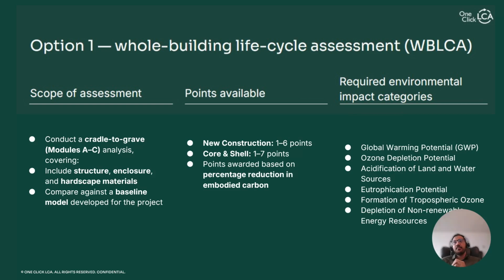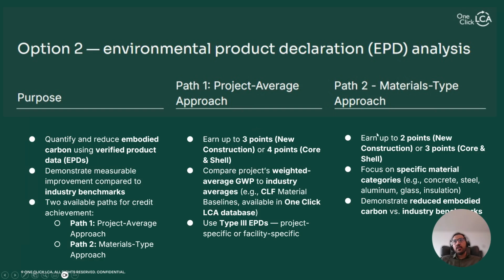GWP, as I said. But for the report, you need to report all these 6 environmental categories, which is going to be available in the TRACI or CML lifecycle impact assessment methodologies. TRACI for North America, and then CML for the European side, rest of the world. You need to consider the CML in that case, but in both of these LCIA methodologies, lifecycle impact assessment methodologies, you need to cover all the 6 environmental categories for the reports for the LEED.